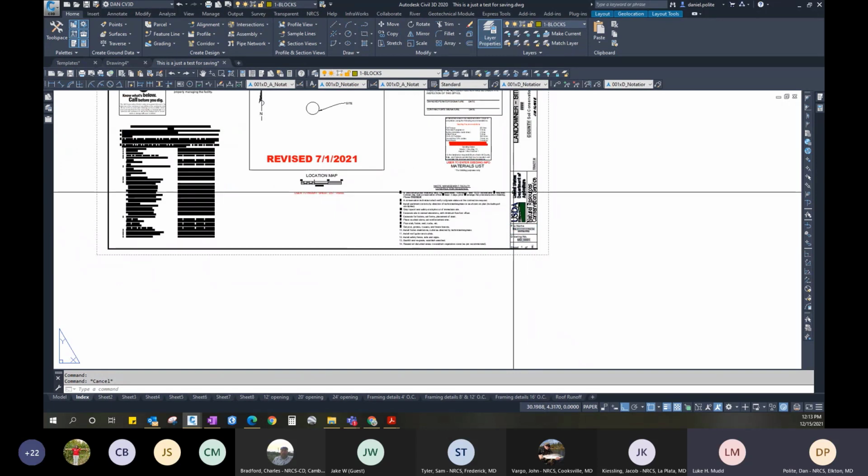I'm hoping that people reviewing these plans are taking out an engineer's scale and double checking the scales, because I've found it too many times where somebody says the horizontal scale is 20, and you go into their actual drawing in CAD, and the horizontal scale is 1 inch equals 40, but it says horizontal scale 1 inch equals 20 on their profile or cross section.